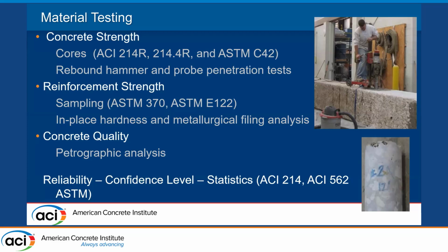Here's the cores. Actually, about the outer 1.5 inches down to 2 inches, these little holes. We discovered a microscopic sponge that was eating limestone aggregate. The biologists were excited. We had a contact biologist say where the holes come from, but the sponges were well satisfied. But that changed the specification in Georgia and Florida. Well, in Georgia right away, no more limestone aggregate near the coast.